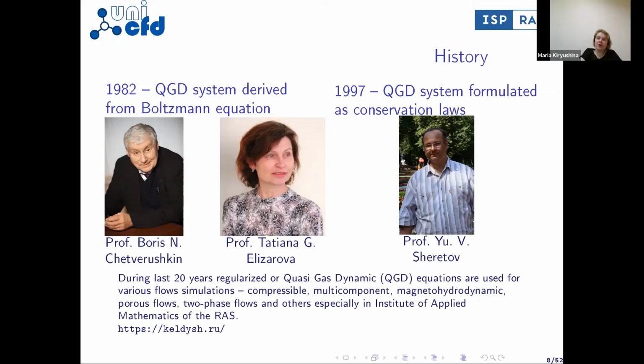The influence of additional terms is inessential for the stationary and quasi-stationary flows for small Knudsen numbers. However, for strongly non-stationary flows and also for Knudsen numbers close to unity, their contribution becomes essential. Precisely in these classes, you can find the advantages of the models. The additional terms manifest themselves as effective regularizers or smoothing terms.